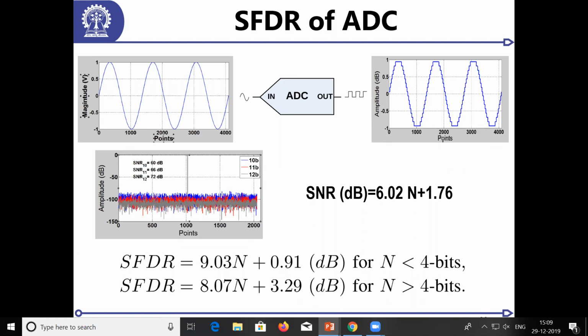Noise is bad for everybody, right? But noise can be beautiful also. So I'll give you a simple example of how noise is beautiful. Let us say we have a 1-bit ADC. The input to the ADC goes from 0 volts to 1 volt. This is the full scale of the ADC. It has only one comparator, and the threshold of the comparator is 0.5 volts.